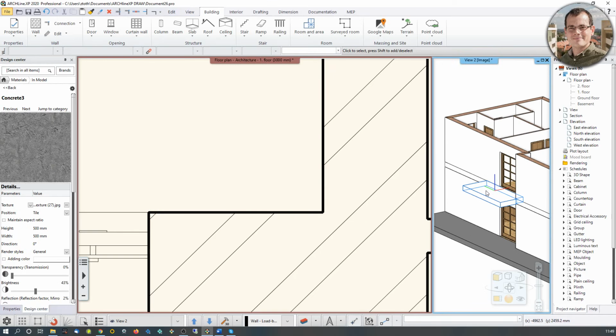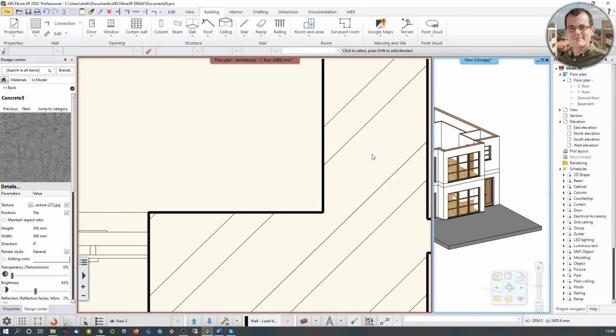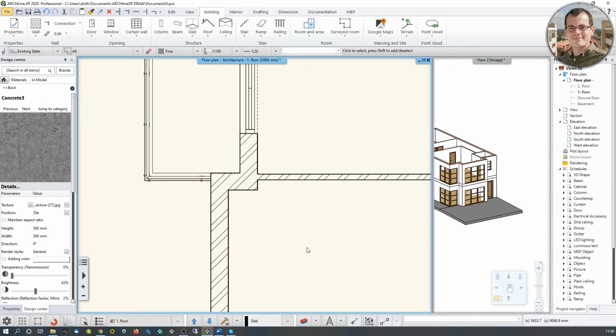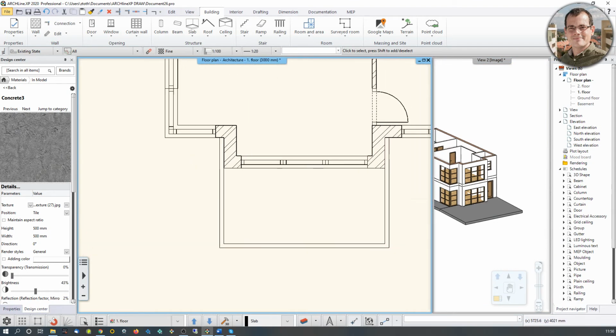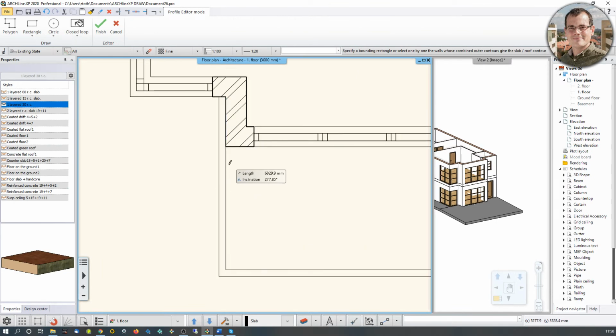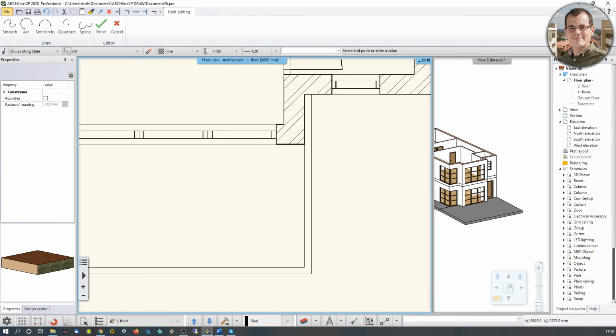I'm going to return here in a second to create a railing, but before that I have to create a roof over here, for which I again have some numbers which I have to pull up because I don't know them off the top of my head, and I have a very nice sort of content here which I can use. You can fine-tune these things as you go, but it's better to get them right on the first try. So here I want to have two slabs on top of each other, which I can create by clicking on the slab tool and first slab in sketch mode, retrace what I have over here,